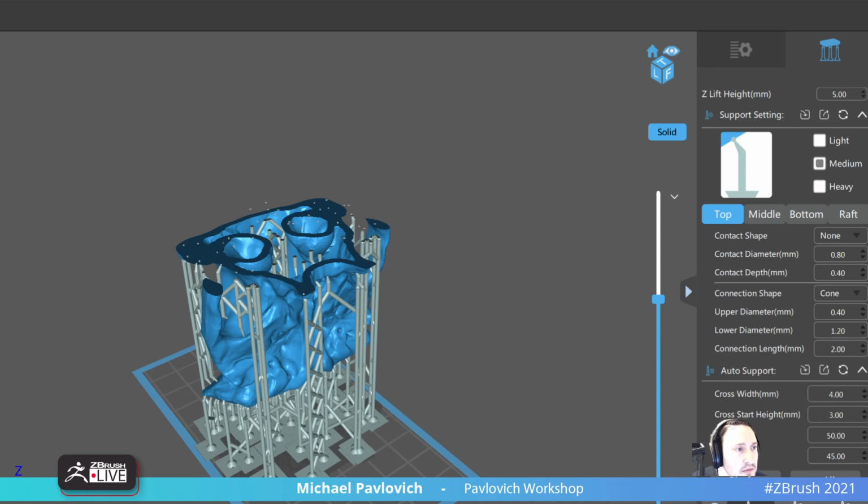Can't figure out how to use Dynamesh for things such as human feet. The toes really stick together. If I use polygroups, then the groups get separated from the main body. Yeah, so what you're going to want to do is not use Dynamesh past a certain point.